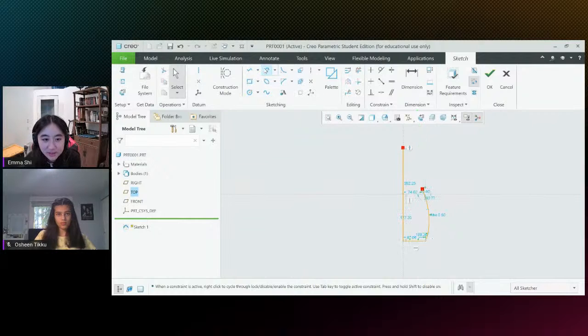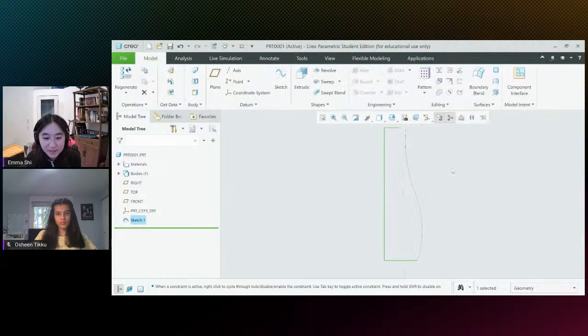Right now, as you can see, the shape isn't closed. That's why there are red lines or red squares. You can fix that pretty easily just by closing them. And then you can seal off the top. Okay, so before it was a little bit angled, but now it's flat. And once she clicks OK, then we have the sketch.